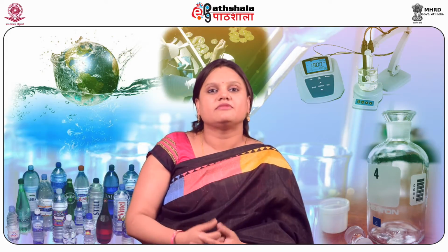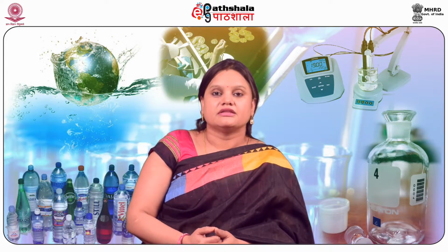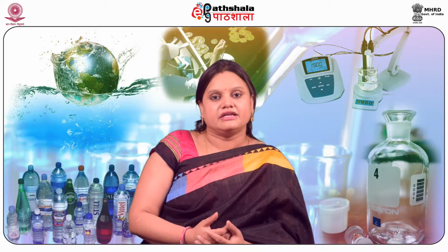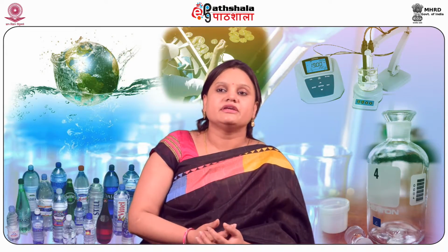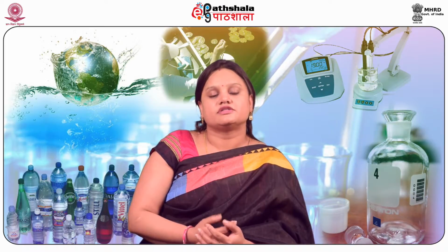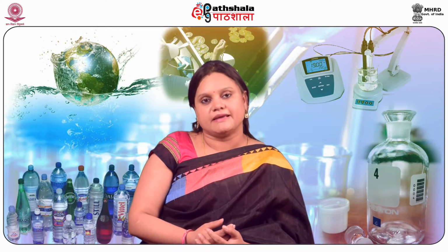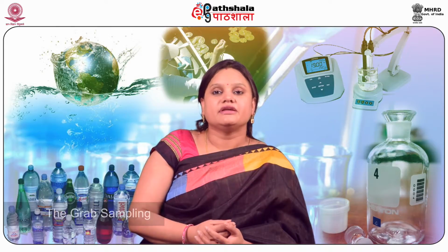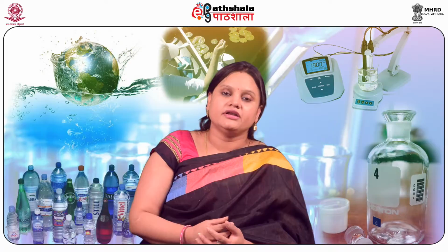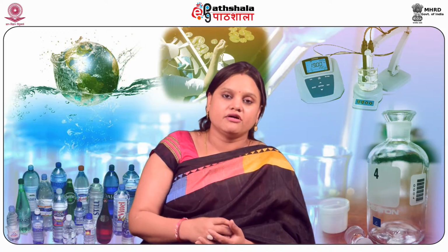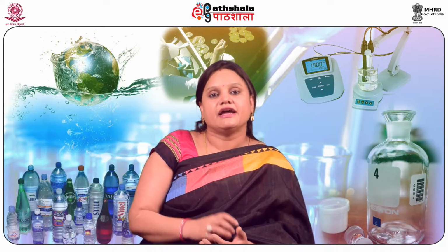Now we have discussed the types of sampling. Sampling is of 2 types mainly, the grab sampling and the composite sampling. The grab sampling is also known as spot sampling and instantaneous sampling. The grab sample is collected at a given point of the sample site and at a given time.